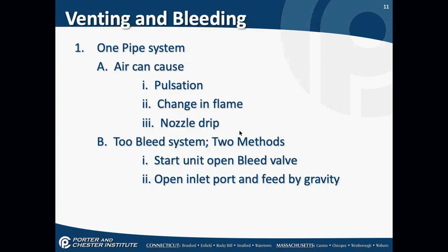If you ever show up to an oil system and there's a whole shield of what almost looks like carbon soot, a hard soot buildup on the end of a nozzle assembly, it's because there's air in that oil line. Someplace in that oil line there is a leak.